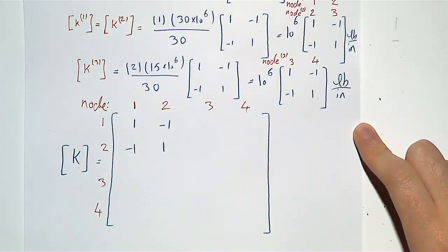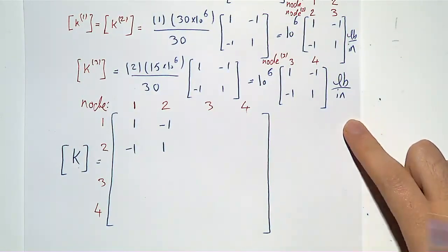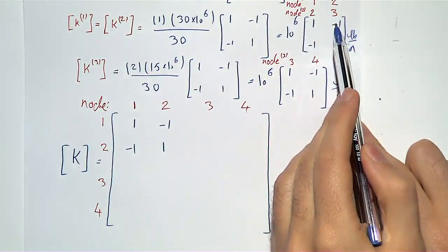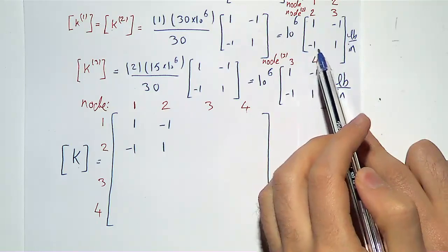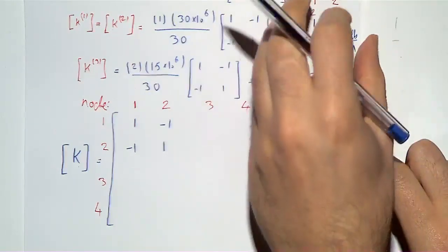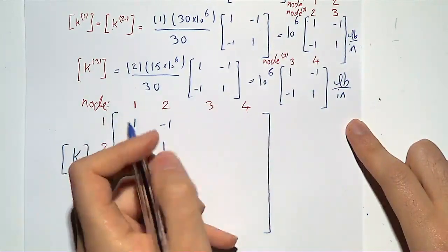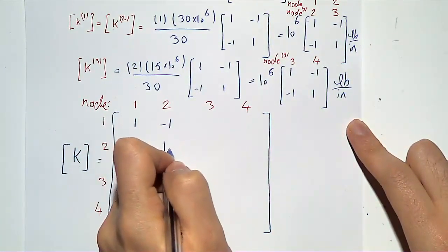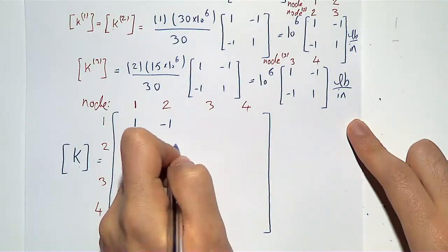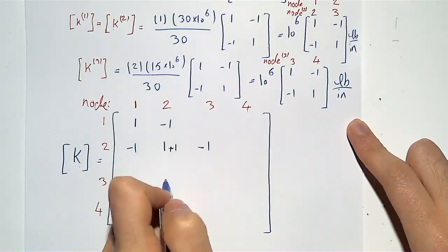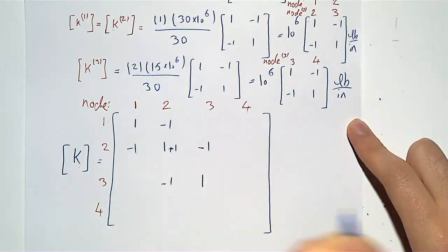And then the next little K matrix, which is exactly the same, but this time it's K22, K23, K32, and K33. So I'm going to put all these 4 entries here. For K22, I have already put one component, so it's going to be +1, -3, -3, and 1.